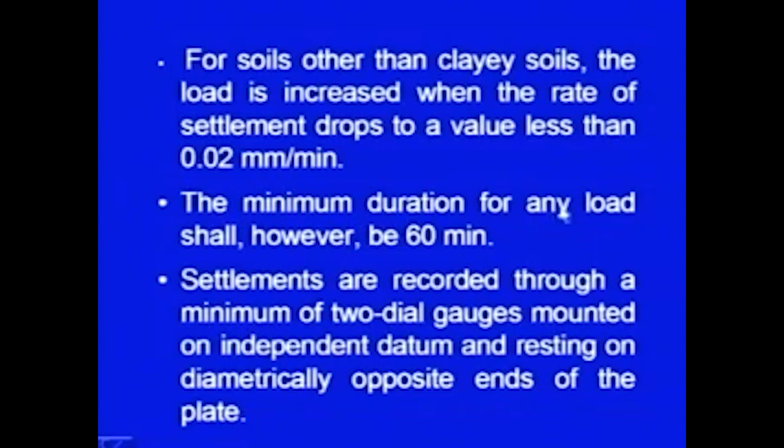The minimum duration for any load shall however be 60 minutes. This is for sandy soils, that at one incremental loading, suppose you apply 1 ton load, at least 60 minutes you have to wait. So, 60 minutes is the minimum time, so that whatever settlement is expected under this loading, it occurs. The settlements are recorded through a minimum of 2 dial gauges mounted on independent datum and resting on diametrically opposite ends of the plate.